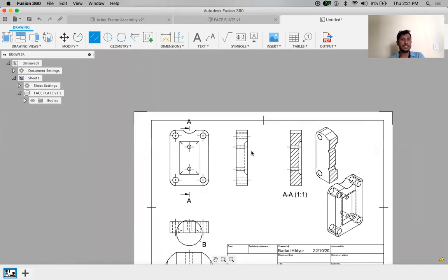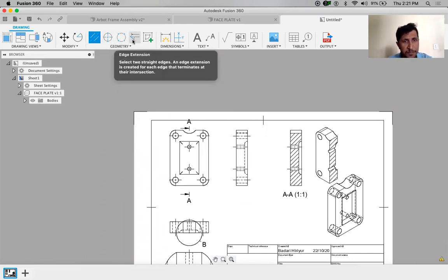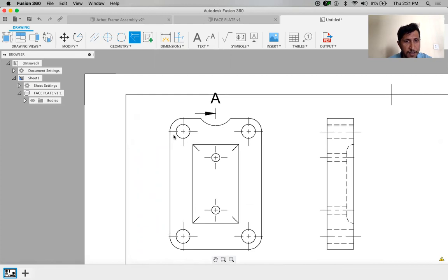So after creating these standard center lines and all, here you also have center mark everything and extension line for your dimensioning purpose. So those things you can also create. For example, I want to create extension line of these two so that I can select this edge for the dimensioning purpose. So you can create that also. Otherwise, you can directly create dimension that will be created from this endpoint. As per the engineering standards, sometimes we prefer to have this extension line for the dimensioning purpose, right?